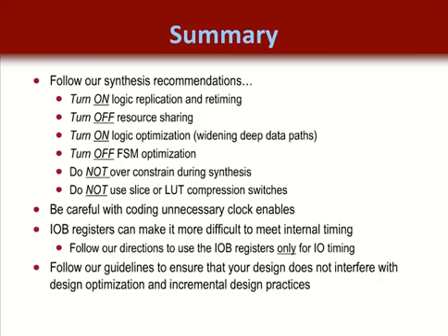We also told you to be careful with coding unnecessary clock enables. Just the same idea with the number of resets, we want to minimize the number of low fan-out clock enables we have in our application. This will reduce the number of control sets we have in our application, again giving the tools more flexibility to meet timing. IOB registers can make it more difficult to meet internal timing, and this is of course because that register is tied to a pin. So that limits the ability of the tools to move logic near that register, forcing sometimes to have longer net delays.